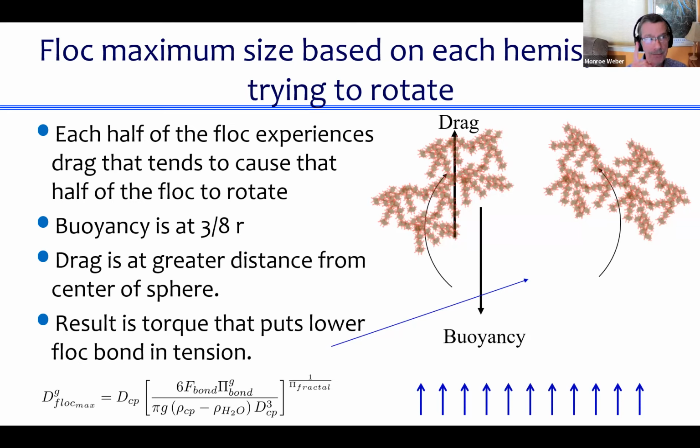It will happen under the worst conditions, and the worst conditions are cold temperatures when things settle slower, and flocs that are super low density, like organic flocs. Those are the ones that won't get to the bottom of your sedimentation tank if your upflow velocity is too high.